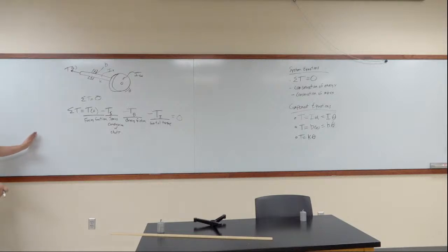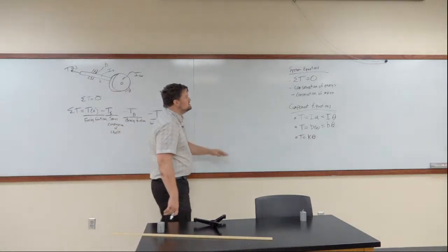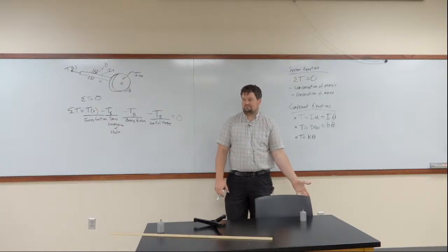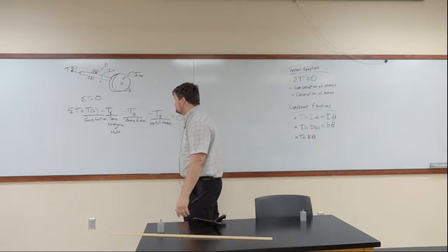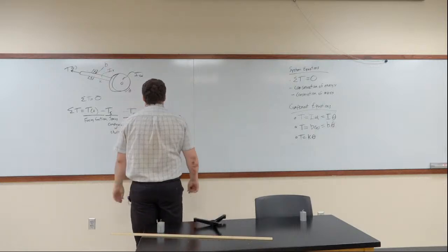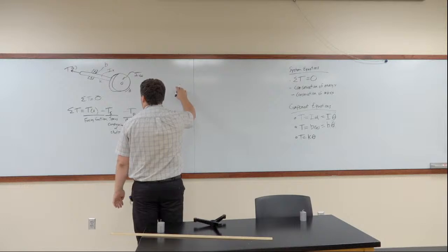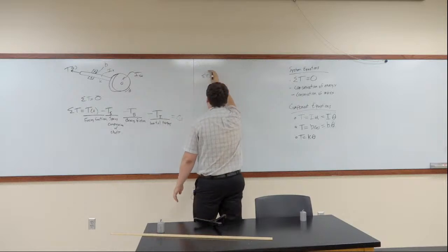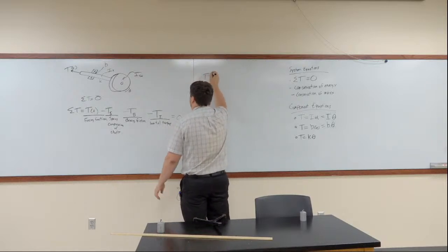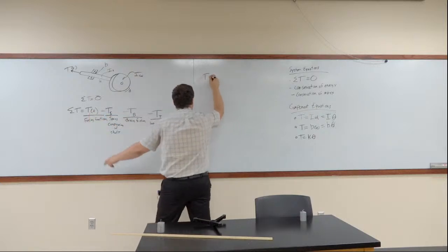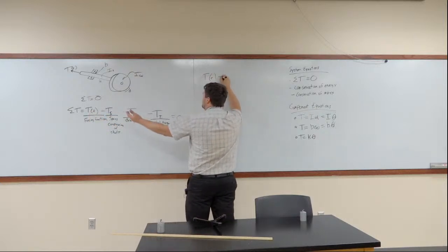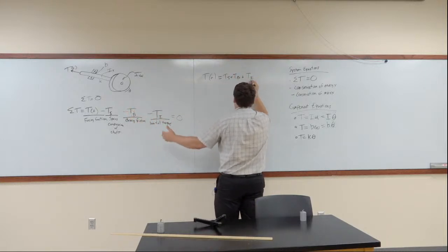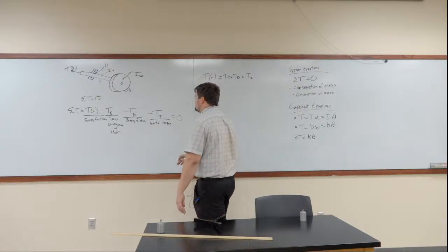Now what I'm going to do is take this equation, which is our system equation, and plug in component equations into it. The torque as a function of time, taking our forcing function out, is equal to Ts plus Tb plus Ti: spring torque, bearing torque, inertial torque.